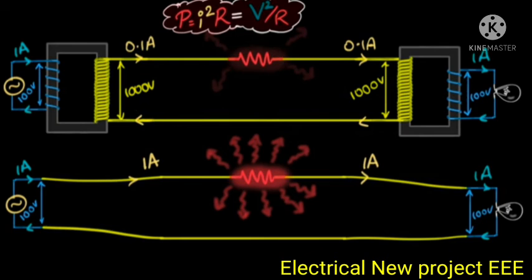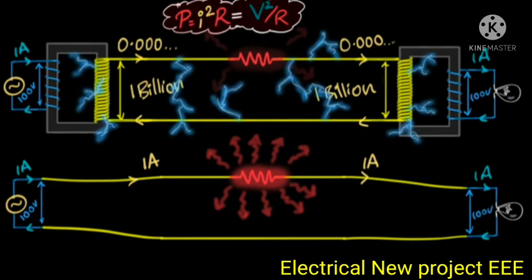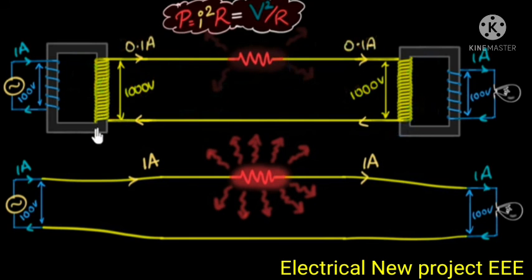And finally, you may be one of those people who might say, why million when we can do a billion? I mean, if you step it up to 1 billion volt, then the current would be almost negligible. You have almost perfect power transmission, right? Well, yeah, theoretically, yeah, but remember, to step up voltage, you have to put more windings appropriately, so good luck with that. But even if you do that, well, there are other problems. Now with 1 billion volt potential difference, we can ionize the air, and that will start giving us lightning everywhere. That's not good. So yeah, there are practical limitations to how high you can go. But if you keep that in mind, then yeah, the higher you go, the better would be the power transmission.